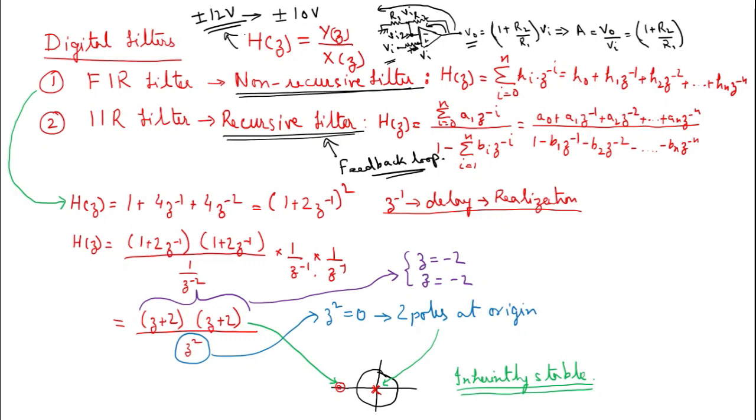Now since it is within the region of plus minus 10 volts, suppose here the gain of the system is say 5. Now if I give 3 volts, it will go and get saturated at 10 volts. Over 10 volts, it will not show any results. So that is the problem with this type of feedback systems. If you do not take care of the system parameters, then you can get unstable readings. So you have to work within a specific input region.